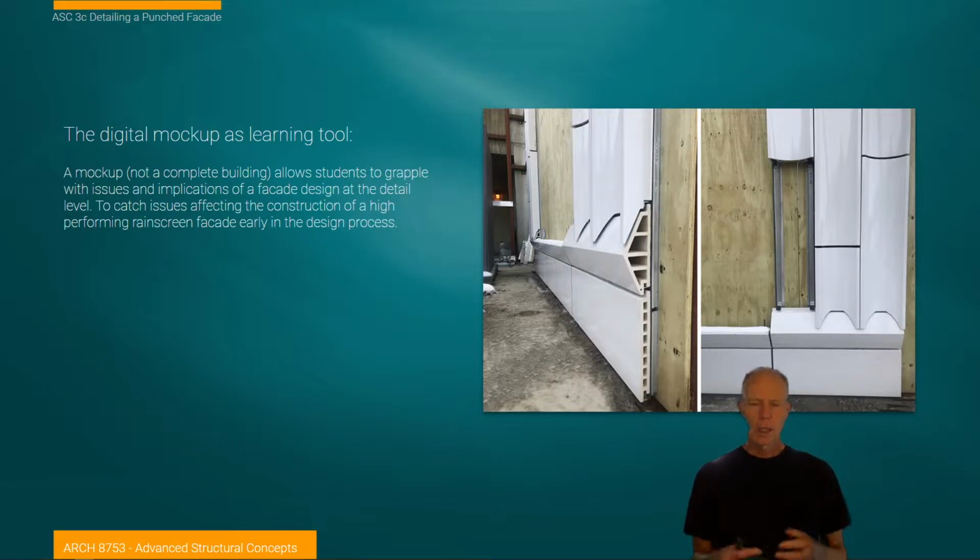So instead of saying, I want the facade to look like this and I make shapes and forms, you say the facade will look like this based on these materials that are creating these shapes and forms, anticipating the need for insulation, the need for thermal breaks, lightweight construction, or mounting systems that maybe don't use aluminum, which has a high carbon footprint. So there's all kinds of this idea of working it into a digital visual mock-up, so you can have discussions with people, run these ideas through your head, and look for opportunities to innovate.